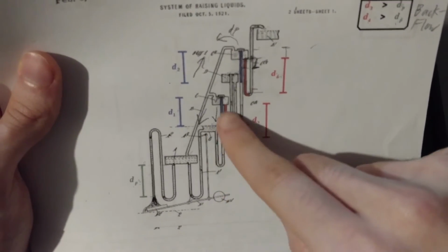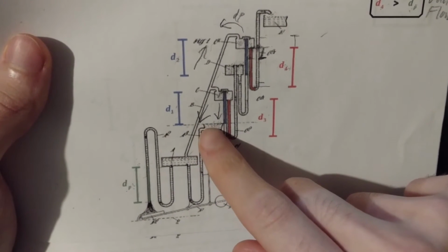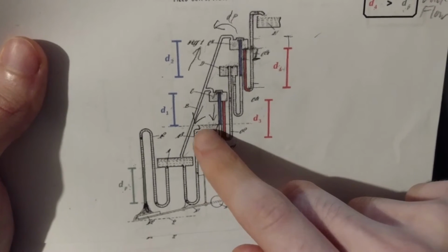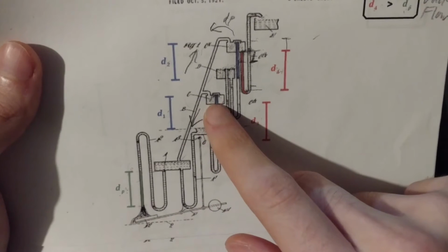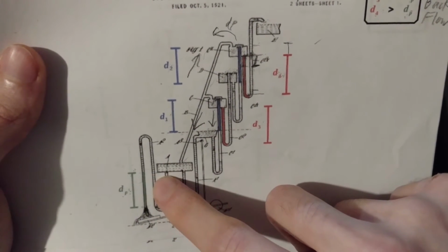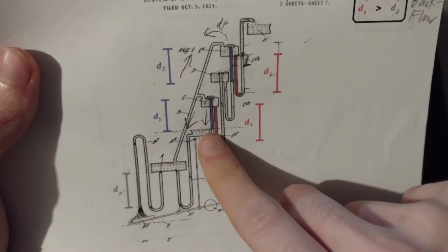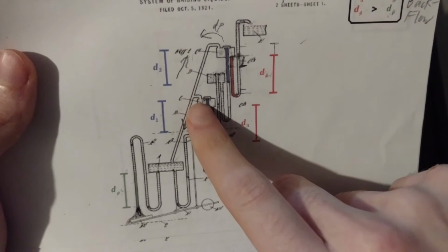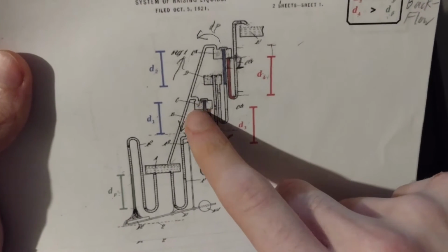It won't have enough pressure to pull the water from this feed tank up through that tube and into the closed container. So that's why you need more negative pressure on the suction cycle than the back pressure from that vertical distance between the water line of the feed tank and the tube at the top of the closed container here.